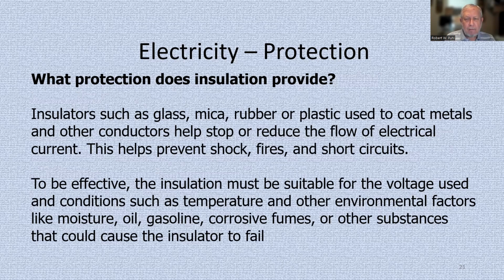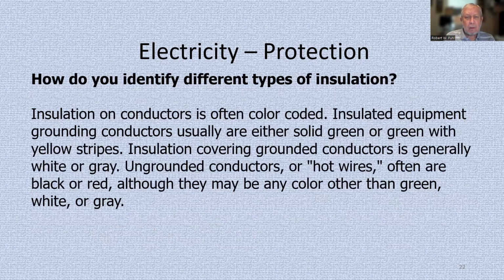This helps prevent shock, fires, and short circuits. To be effective, the insulation must be suitable for the voltage used and conditions such as temperature and other environmental factors like moisture, oil, gasoline, corrosive fumes, or other substances that could cause the insulator to fail.